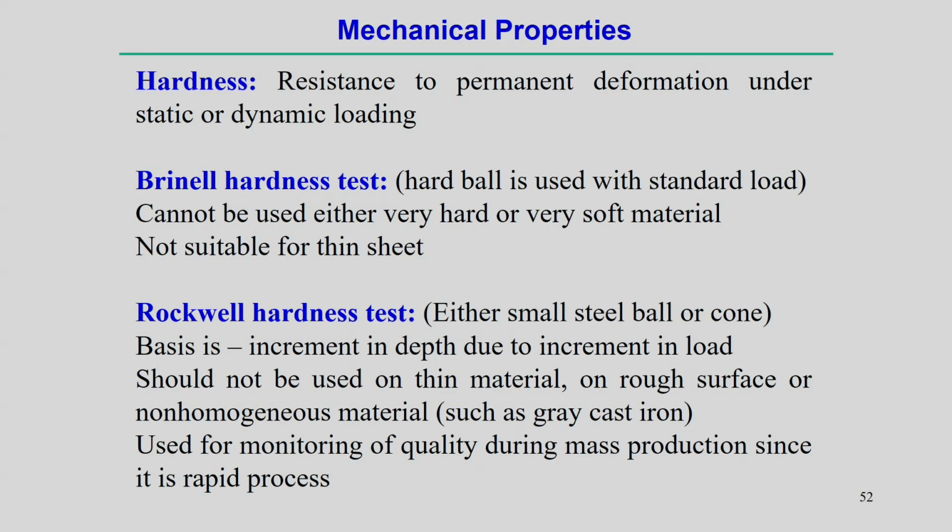But there are different technologies, basically different methodologies, to measure hardness. First is the Brinell hardness test. In these cases we use a hard ball.